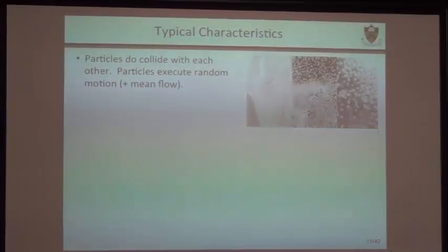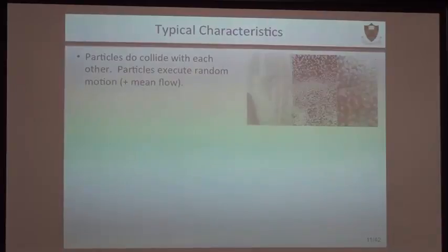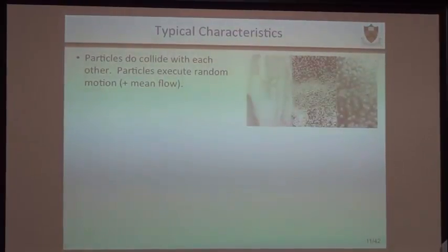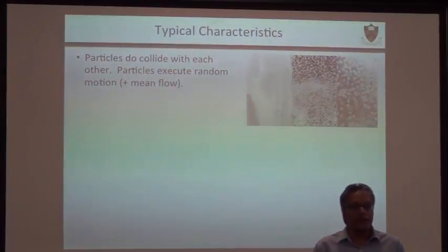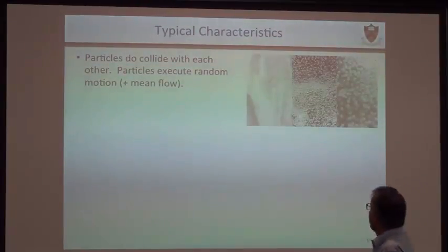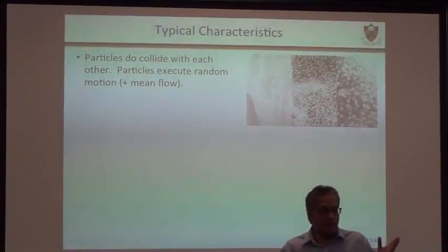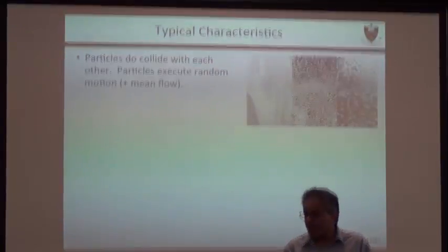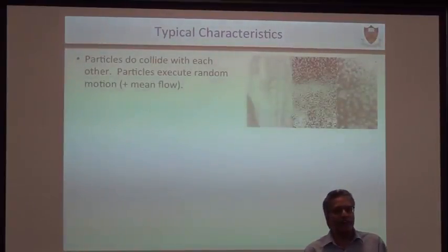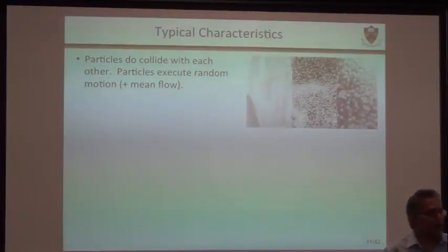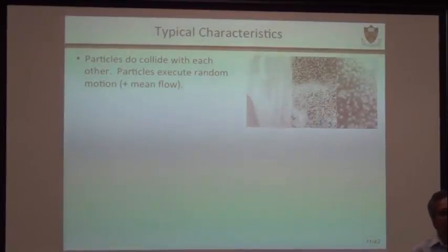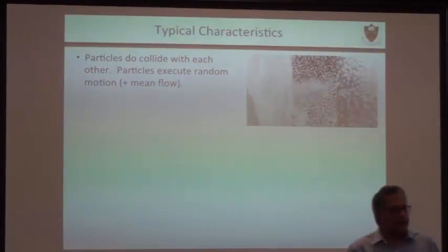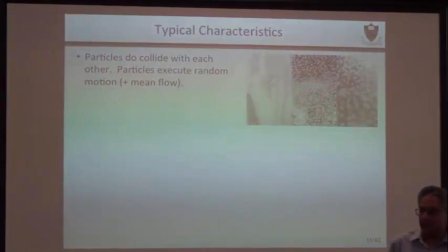If you look at this kind of flow problem, you find that particles do collide with each other, and then they execute the mean flow, they will also execute the random flow. And this has led to a theory called kinetic theory of granular materials, where particles are treated essentially as large molecules, and the kinetic theory of gases has been adapted to describe the flow problem. That's a fairly mature field where people have worked for over 25 years. So we have come a long way in saying that those types of descriptors do a decent job of capturing the effects of small scale dynamics of the particles.